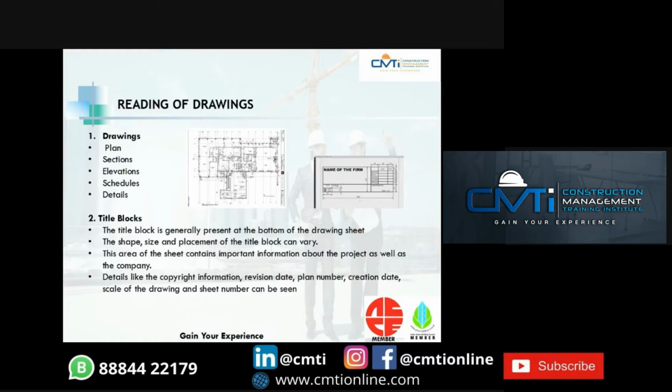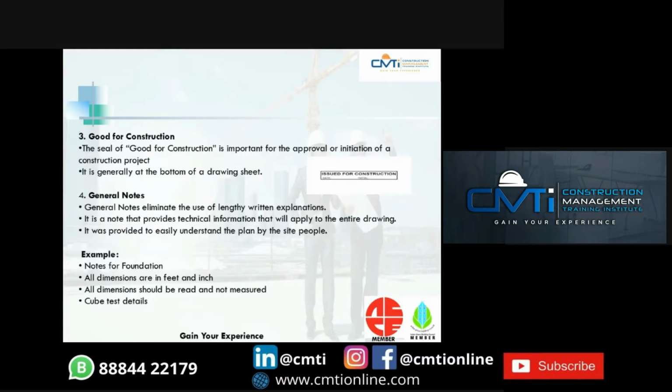Above is a title block. There you can see the name of the firm, the title, and important information regarding the project. So the details like the copyright information, revision date, plan number, creation date, scale of the drawing, and sheet number can also be seen in the title block. Next is the good for construction stamp. The seal of good for construction is important for the approval or initiation of a construction project. So basically, if you don't get this stamp, then you can't start the project because there's been no approval or initiation. And next one is general notes.